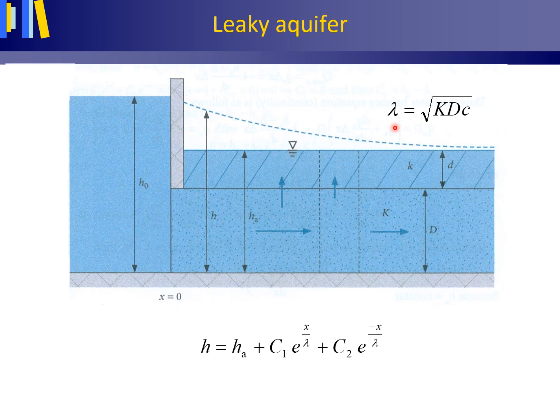Conversely, the leakage factor is small when the leaky aquifer has a low transmissivity, so a low Kd value, and when the hydraulic resistance C of the confining layer is small. Vertical seepage through the leaky confining layer then dominates over the horizontal groundwater flow through the aquifer, and then as a consequence in this Hollandse profiel, the hydraulic head in the aquifer then decreases relatively fast with distance x from the left canal.